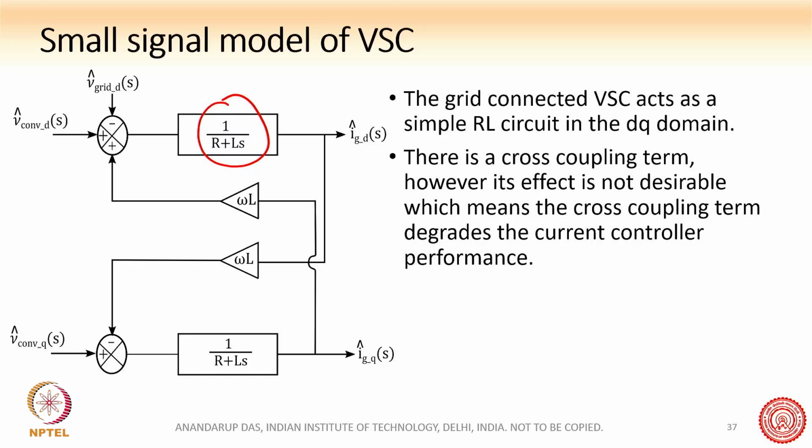So all these delays in the system have now become very, very small. So our assumption that these delays are negligible with respect to the controller design is very reasonable and is a quite accurate representation of what modern power electronic systems, modern grid connected VSCs, are operating with. So with those necessary approximations, our model becomes very simplified. The model has precisely this R plus Ls term.